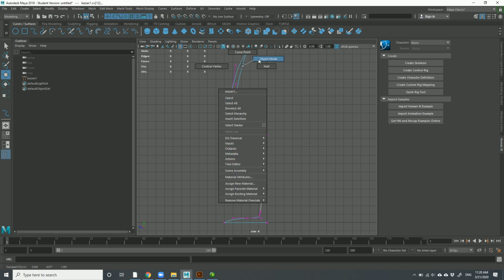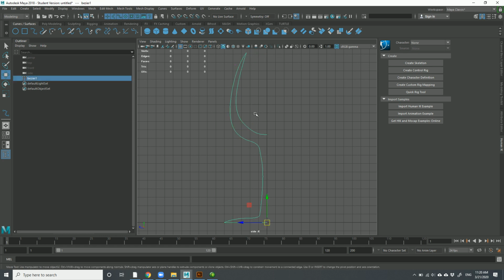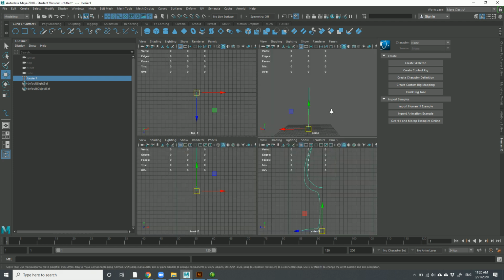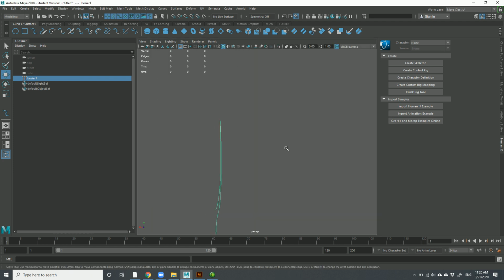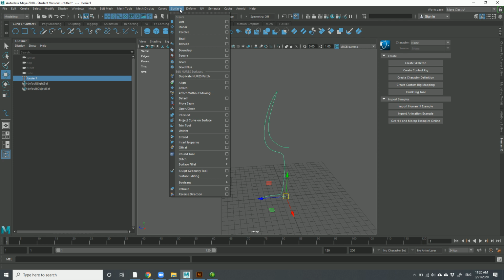And so I've got this object here, and we're ready to make the wine glass, for example. So if I take this, let's go into 3D here, to my perspective view, and you see I've basically drawn the profile of this line. I can come up here to where I've got this little picture of a wine cup kind of, and this is the Revolve command. You can also find it here, just like I was saying earlier. You can also find that command as well as lots of others under here.